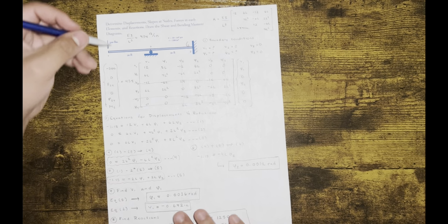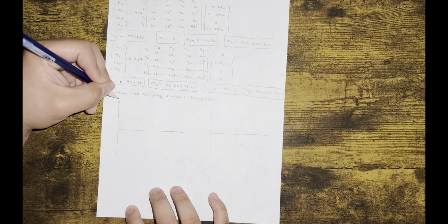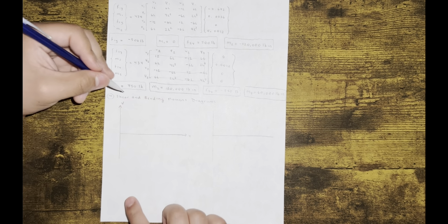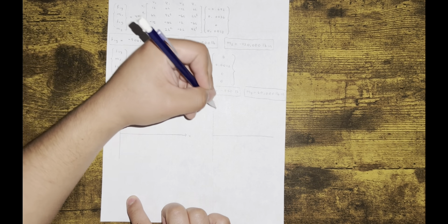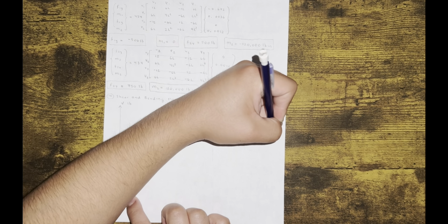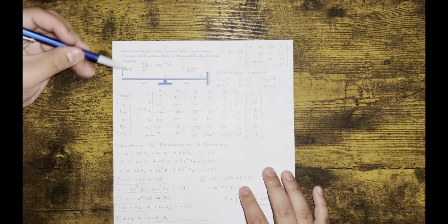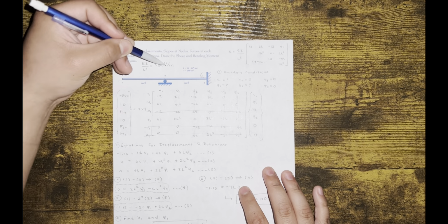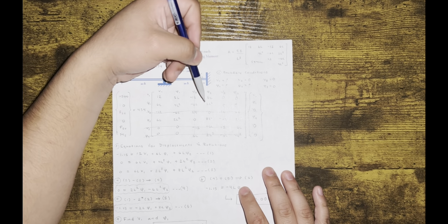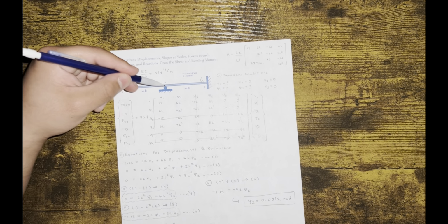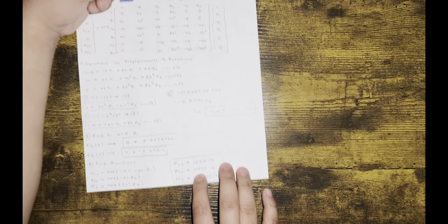So we start here, and this doesn't mean it's fixed, okay? It's just an axis. That's right. V, X. In this case, this is in pounds. This will be moment, pound-inch, and then along your beam, along your X direction. So 500 pushes down, nothing. 1250 pushes up, nothing. 750 pushes down, right? Again, 500 pounds going down here. This reaction's 1250 going up, and this one's going down, negative 750.